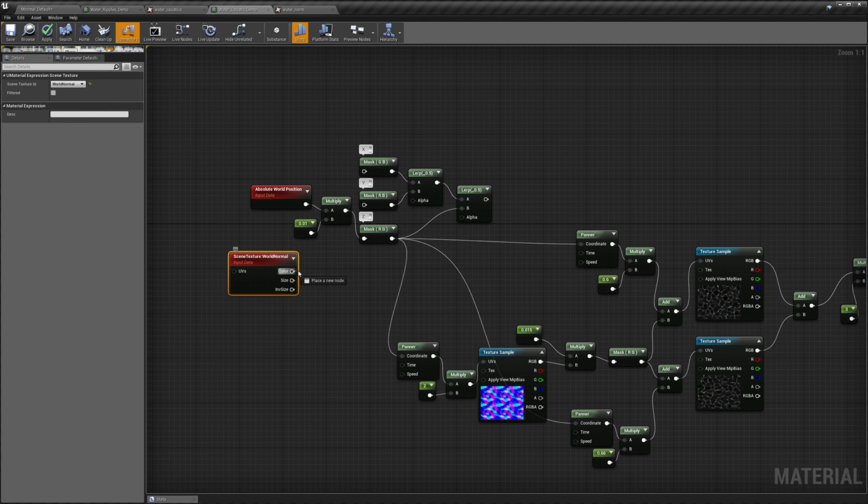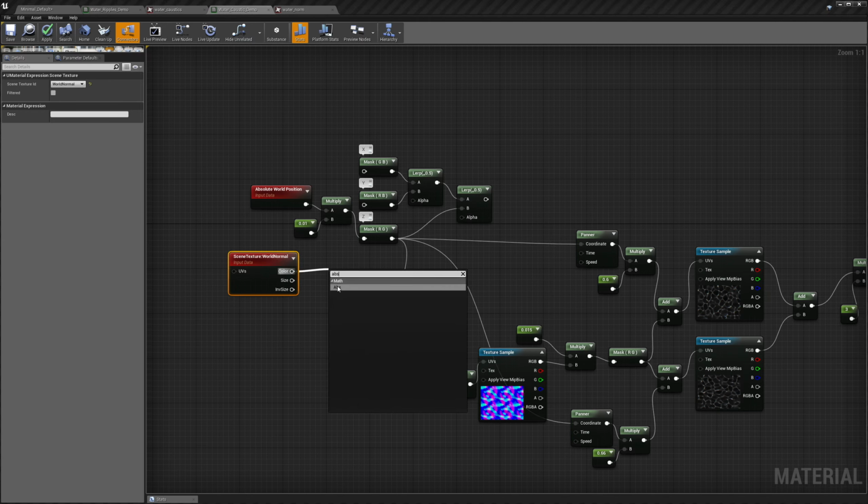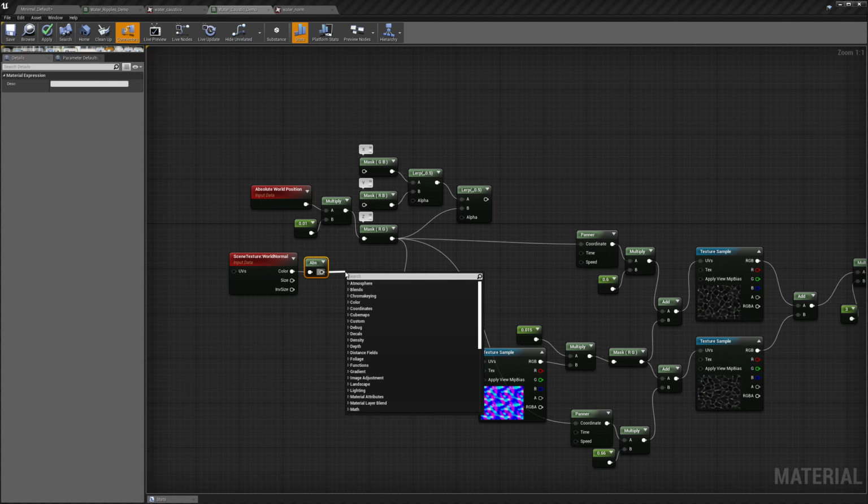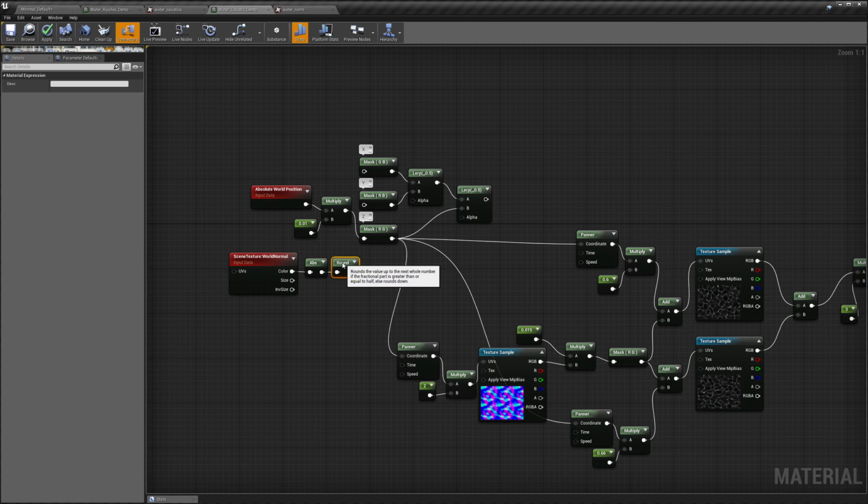And that's pretty cool because it means I can get whatever direction my scene is facing and bring that into my scene. Now I want to take the absolute value of that normal, and now I want to round it. Because I'm creating masks, I just want to round it between 0 and 1. I want to know, am I facing in this direction or not? So I'll take my absolute value and round it. And now what I get is, this has 3 different values, and they're an answer to a yes or no question. Am I facing X, am I facing Y, or am I facing Z?